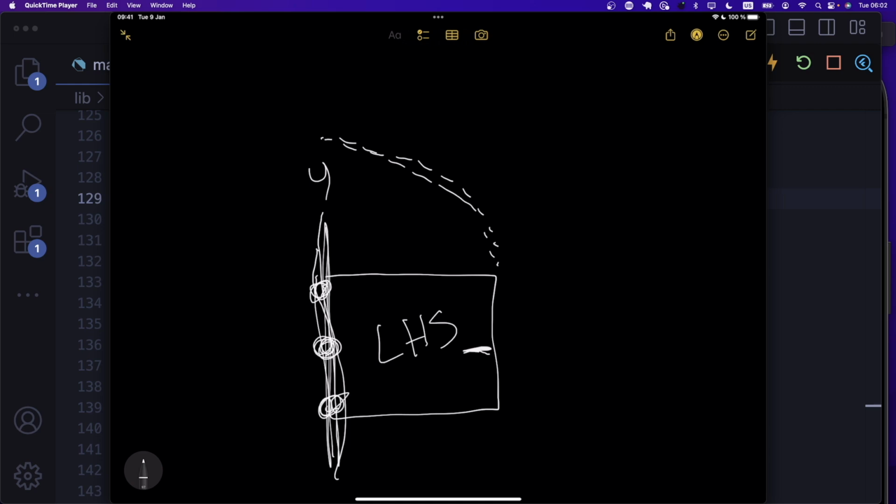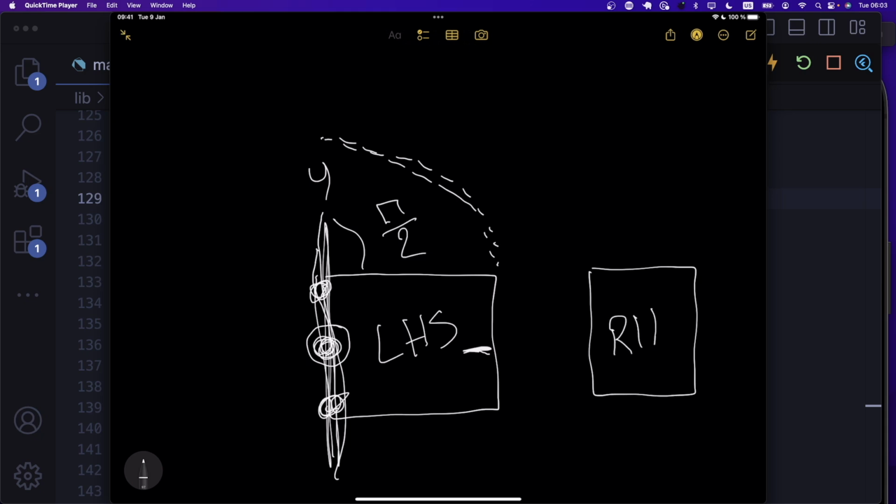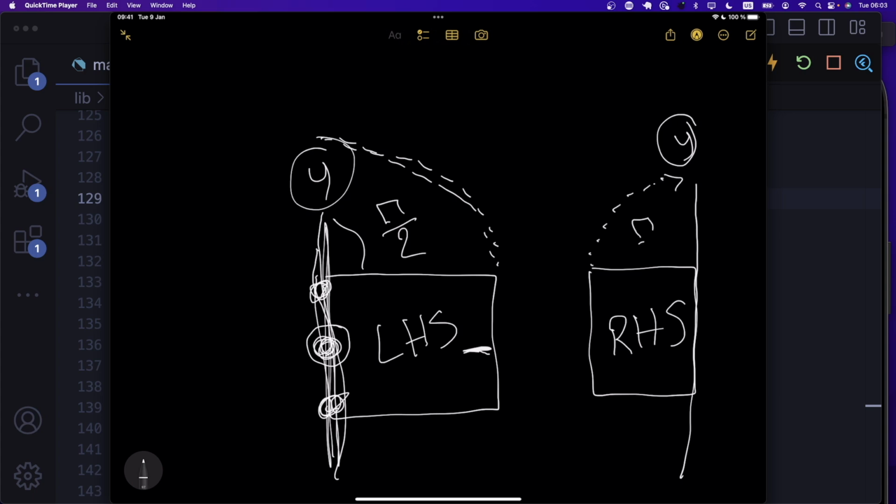How can we specify that? Well, that is using transform and its alignment. So we're going to say alignment is center left, and then we're going to pivot it 90 degrees, or pi divided by 2, onto the y-axis. The same thing we could say, maybe I should explain it right now. If we have the right-hand side of the cube, then we're going to pivot it around the y-axis again. Both are y-axis. We're going to pivot them 90 degrees, or pi divided by 2 again.